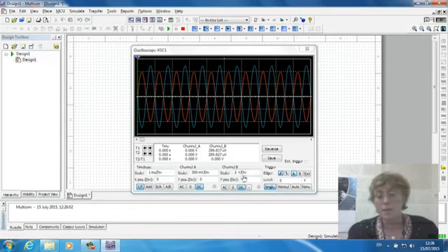I also put in a 2 volts, we're expecting an amplification of 5. So our 1 volt should become 5 at the output, so we can check we're on 2 volts per division on the output, so we've got 2, 4, and probably another half in each direction would give us 5 volts. We can also measure those using the cursors here.